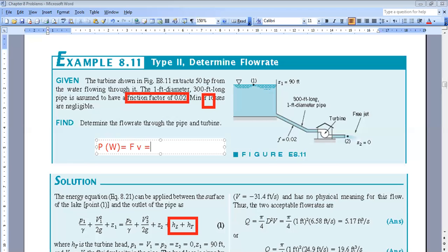Or here, because we have pressure, we can replace F by pressure times area times V. So this is why for power, here I will put power to not confuse it with P, okay? Power is pressure times what? What is AV? It's the volumetric flow rate. So power is pressure times Q, the volumetric flow rate, okay?